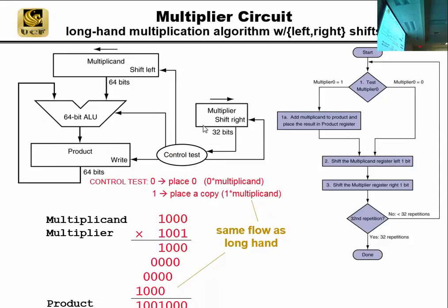This is from the book, so we show you this first, and I have about 12 slides that break it into steps. I think it's clearer, but here's the overview. We start with the multiplicand and multiplier that you want to multiply. This is loaded right justified, and every time we go through this loop, which is 1 bit, we're going to shift it to the left.